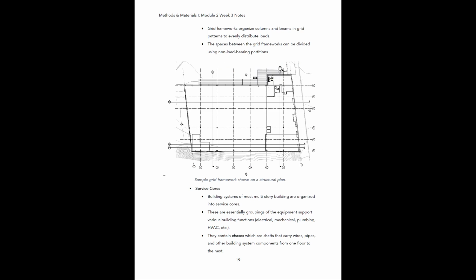All right, so if you look at this drawing, it's a drawing from Revit or something, but basically what you're seeing here is a series of columns, okay? The columns are occurring on these grid line intersections. So we have some dots here, here, here, and here, and then again, here's another row, and all these little dots are representing columns, okay? These dashed lines are the column lines or the grid lines, and these will be denoted using letters and numbers.